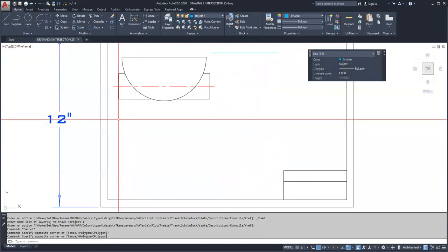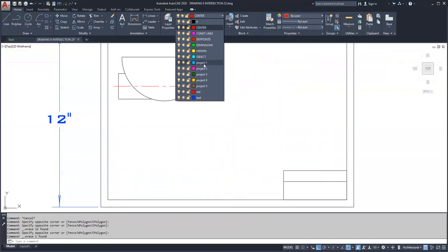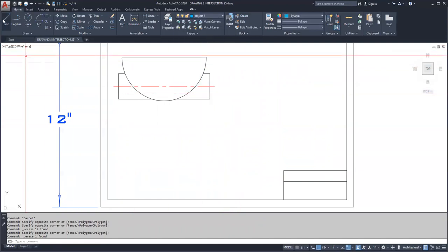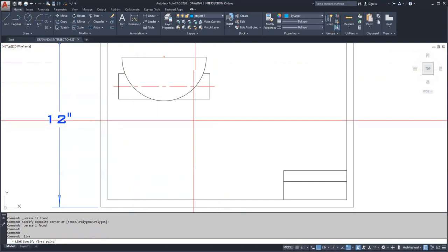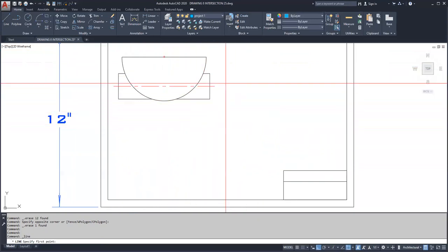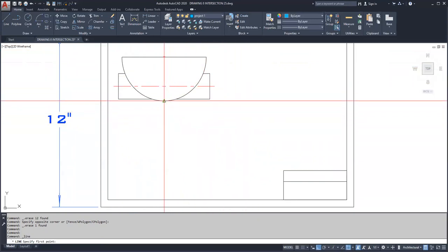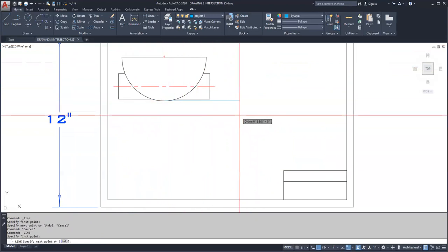These are old projection lines. Let me erase those fast. Now, people always ask me, how do you get the 45 line to project for an orthographic projection? It really can work with multiple points, but usually I say the lowest point of the object. So the lowest point is right at the bottom of the circle here.